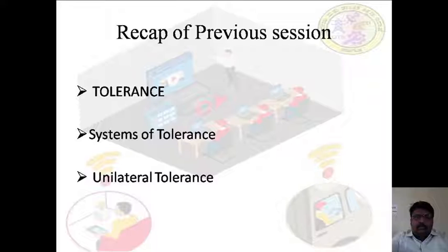Variation in size or dimension is called tolerance. Thus, the word tolerance indicates that a worker is not expected to produce the part of the exact size, but a definite small size error is permitted. The difference between the upper limit and the lower limit of a dimension represents the margin for variation in workmanship, and it is called the tolerance zone.